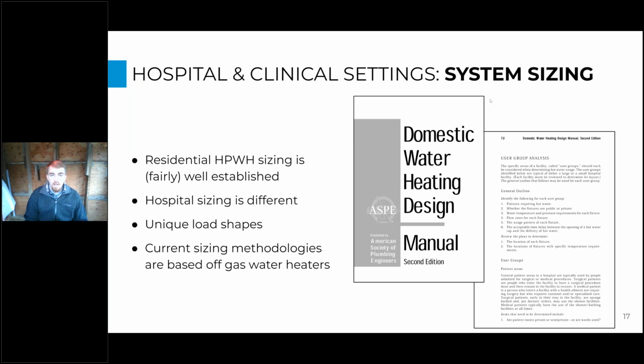And so one source that has a lot of really good questions around this is the Domestic Water Heating Design Manual by ASPE. They talk about different user groups and different usages that you might expect in hospitals, and they talk about the questions that you should be asking these clients to basically build out that load profile throughout the day. So then you can implement the storage size to handle those really high peak loads when a lot of uses overlap, and then you can determine how much recovery you need to recharge that storage throughout the day.